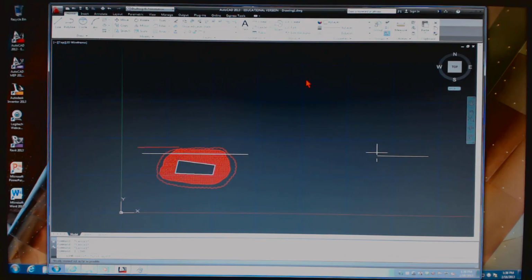Okay, if I was going to draw a door that's 3 feet long. Okay, so my door right here is 3 feet, my opening is 3 feet. Now a lot of times, I don't show mine all the way open like that. I like to show mine partially open. It just gives me more room to do things on the house plan. That's just my preference. But you got to show a door swing.